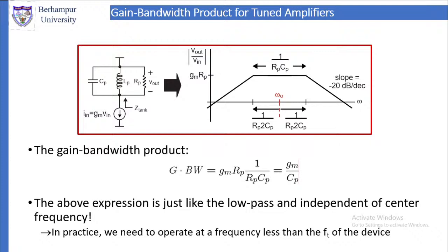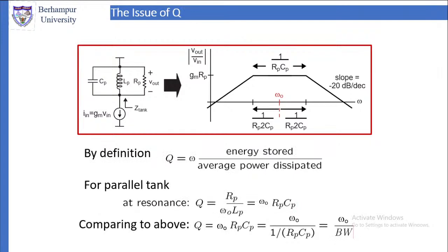So this expression is just like the low pass filter, and it is independent of the center frequency omega 0. This expression does not depend on omega 0. But in practice, we are required to operate at a frequency which is less than Ft of the device. So omega 0 has to be less than Ft of the device. That is the caveat.